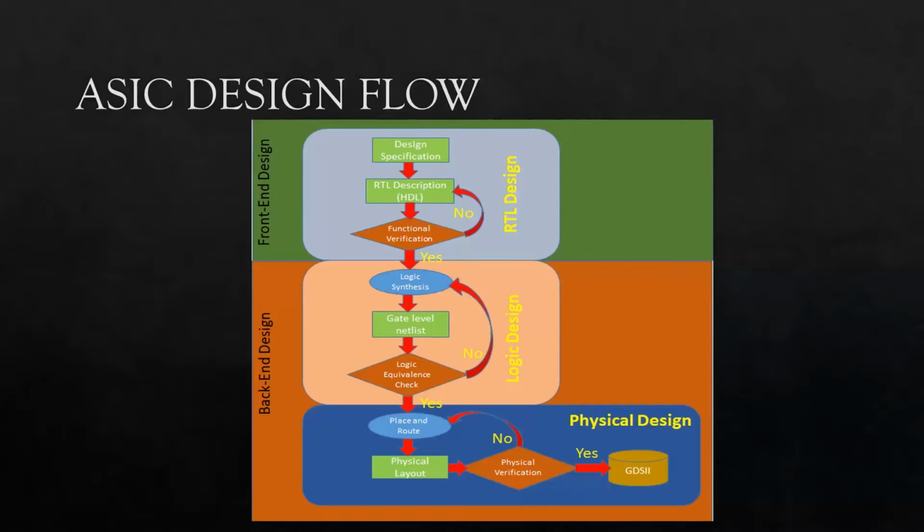The verification engineer will first go through the technical documentation of the RTL design engineer, and point out each and every feature: what are the features I need to verify? Based on those features, the verification engineer will first make the test plan. Once the test plan is done, based on priority, the tests are executed one by one.